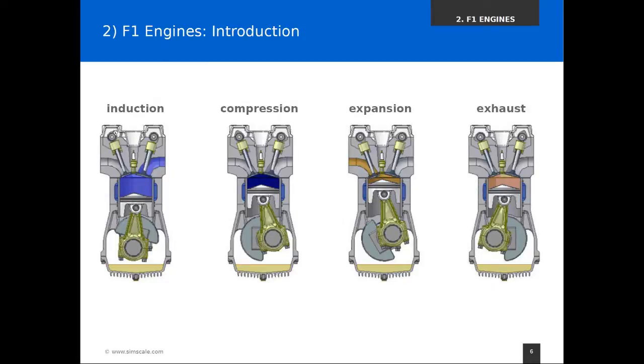And this is just another shaft which also rotates, and as you can see, it's not fully symmetric, and as it rotates, it will push down the valve, and when you push down the valve, it opens it, and then if it turns a bit further, then it closes again. So this part here is the camshaft, and usually the camshaft rotates at half the speed of the crankshaft. Both of these are linked kinematically together, using gears or a belt drive.